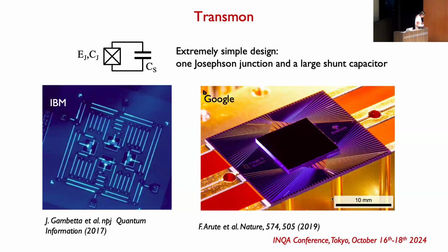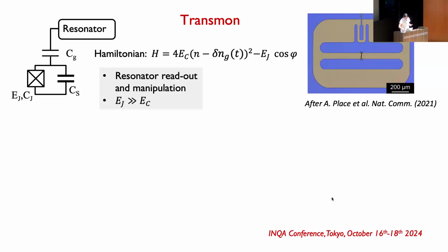What is the most important, let's say, why is the transmon so common and so successful? I think we have already heard from the talk of Nakamura. The crucial point is its simplicity. The strength lies in its simplicity. It's just a single junction and the capacitor floating essentially, no connection. And this extremely simple design also protects it from external noise sources.